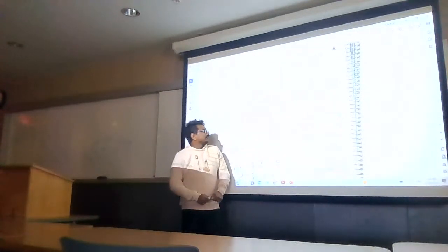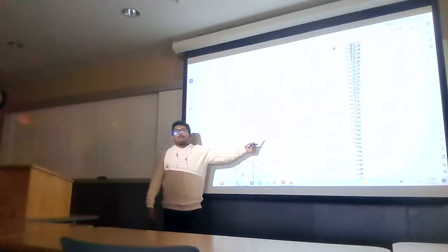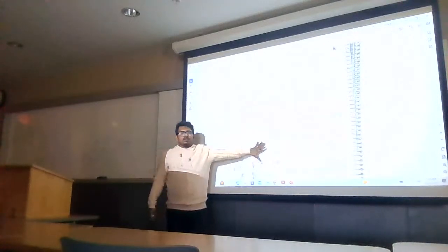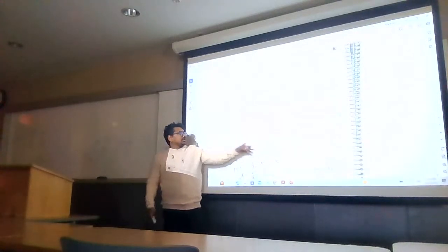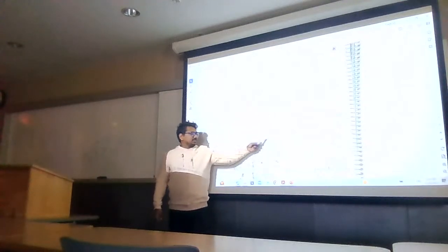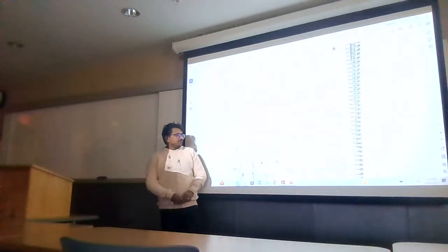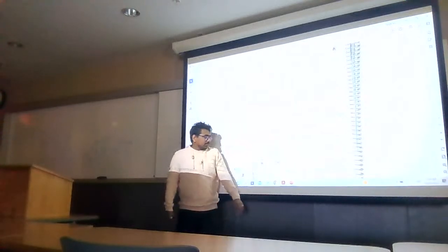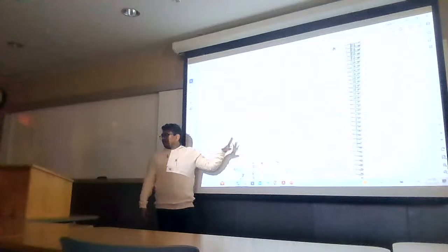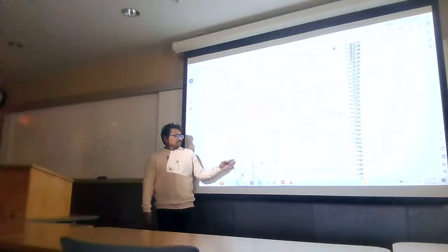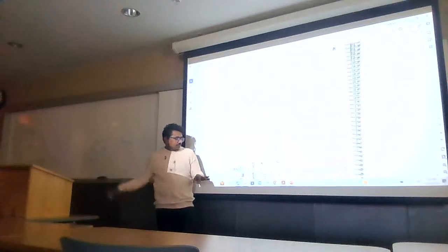At higher frequency, there will be some parasitic capacitance. In a MOSFET there are a couple of parasitic capacitances, and if you study the Miller theorem, you can find the existence of parasitic capacitance. At high frequency, we have to consider this parasitic capacitance also. But these types of questions are very common in interviews: find the input resistance, output resistance in different conditions, as well as the small signal model.